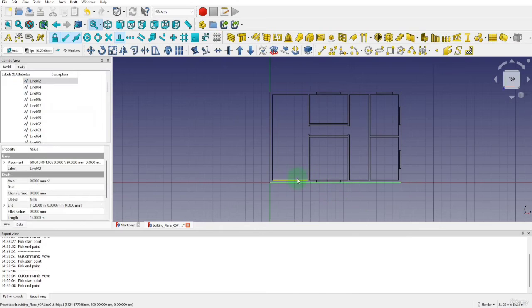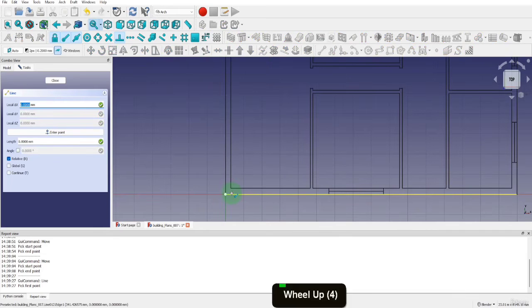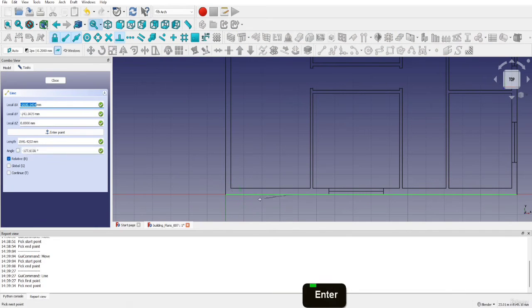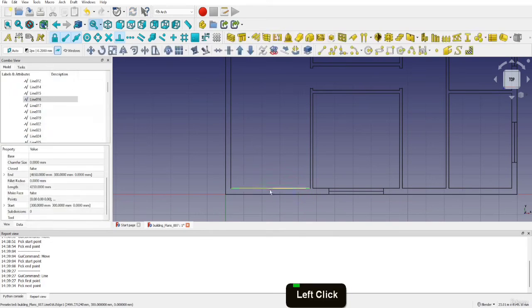On the left side of the building, there is a large window running around into 3700 from the end. We can draw this in now. Let's switch back on construction mode. Select the line tool and we can hover below here. In the X field, we can input 3700 and press enter. That's the first point, so drag up and press Y to lock the axis. Now snap up to the height.